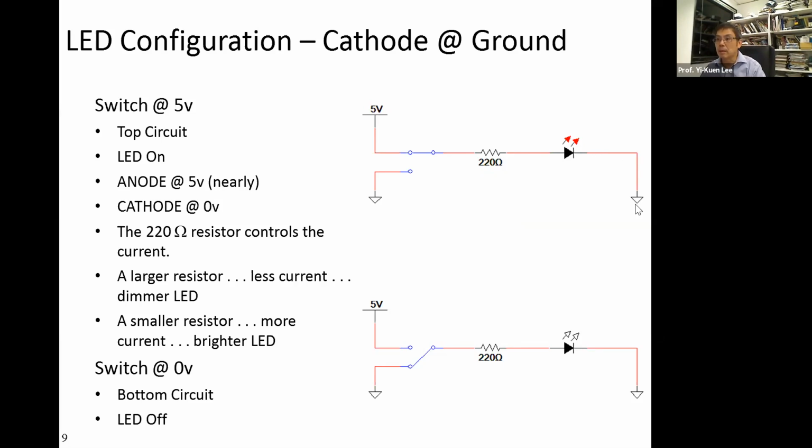In this case, what happened? We can do some simple calculation. If you turn on this 5 volt here with a switch, then we can turn on the LED. If you turn it off so that it is grounded, then both sides of this LED terminal are grounded, and we have no light from our LED, right? So that's the basic thing. That means you can do some simple switching. So how can we do the switching with our Arduino?